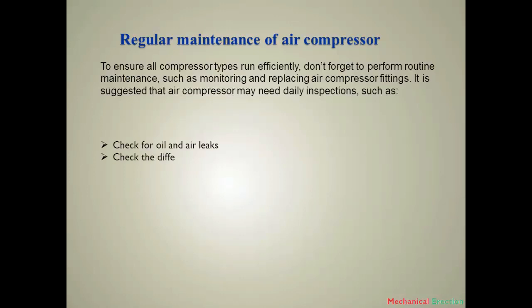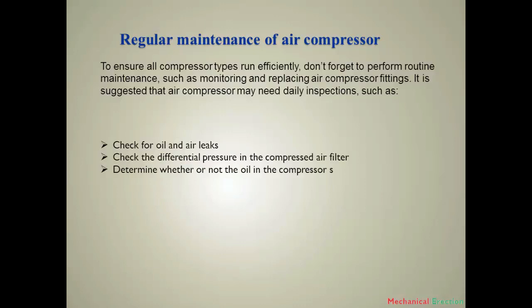It is suggested that an air compressor may need daily inspections, such as checking for oil and leaks, checking the differential pressure of the air filter, verifying safe operating temperature to avoid overheating the unit, and determining whether or not the oil in the compressor should be changed. These are the regular checklist. You should check this regularly.